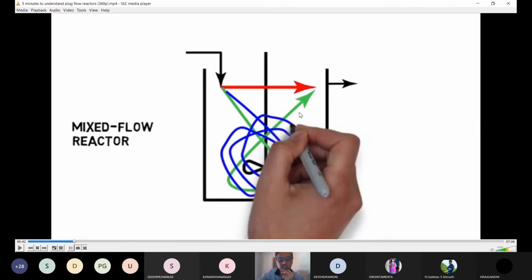That's what is explaining. ये नॉन आइडियल रिएक्टर की बता रहा है कि ऐसा क्या होता है, when you add reactant at the top, some molecules will directly go from inlet to the outlet, so they'll spend very less time in the reactor. Some molecules will go in a different flow pattern, तो यहाँ पर ज़्यादा टाइम रहेगा। और कुछ मॉलिक्यूल ऐसे घूमते रहते हैं, कॉर्नर में जो रहता है ना, पॉकेट्स बोलते, डेड पॉकेट्स बोलते हैं। तो यहाँ पर कुछ अगर मॉलिक्यूल अटक गया तो अटक गया, निकलता नहीं, because mixing generally यहाँ पर होता है ज़्यादा, बीच में, नीचे कॉर्नर्स में नहीं होता इतना एफिशिएंटली। So that's why some molecules spend less time in the reactor, कुछ spend more time, कुछ spend many more time, कुछ spend a lot of time. And that is a non-ideal reactor.